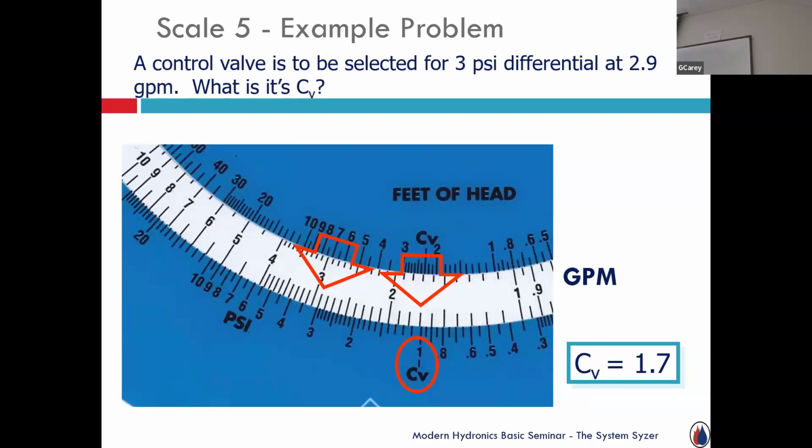Like a control head. I'm not sure, but I think we're going to go there because we're going to get into variable speed pumping where we have control head that we have to account for. Yeah, but there is a reason. I think the reason I'm going to discuss is going to maybe correspond to the kind of industry statement that's said quite often, that there's going to be a control valve pressure drop relative to the overall system pressure drop.